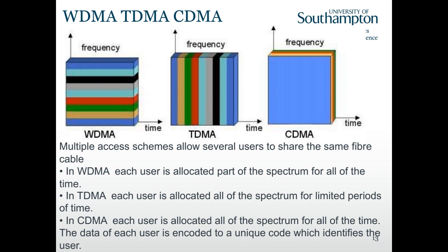Okay, so we are going to talk about multiple access in optical communication. This is quite similar to RF, radio frequency wireless communication. Basically, we can separate different users by wavelengths. Each wavelength corresponds to a frequency, so this is equivalent to FDMA in RF. Different users are differentiated in different channels. They use different channels, so they wouldn't interfere with each other.